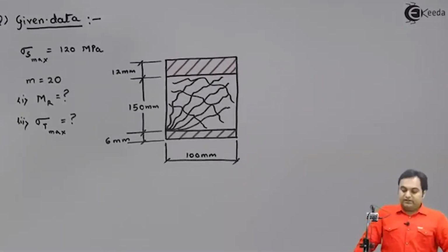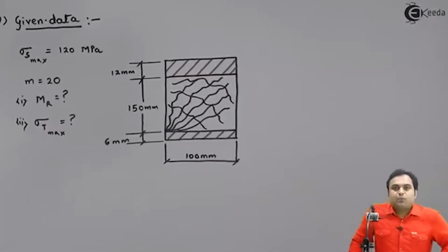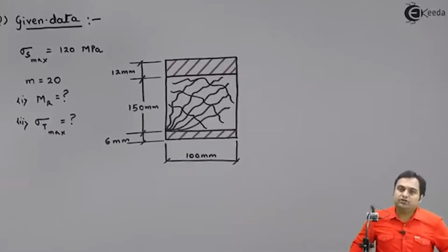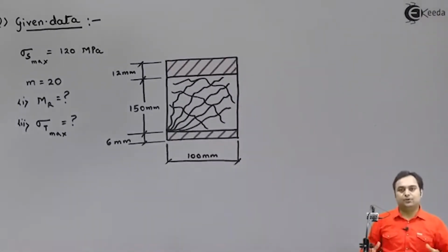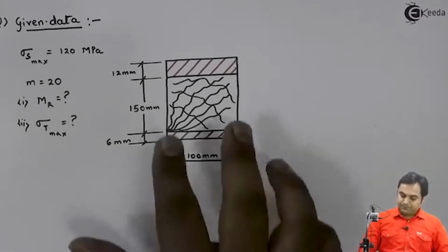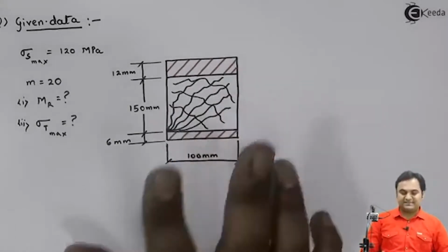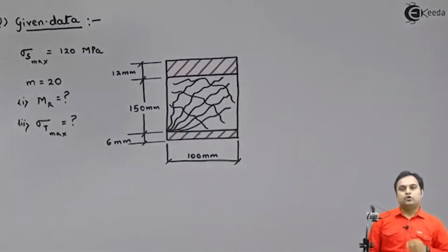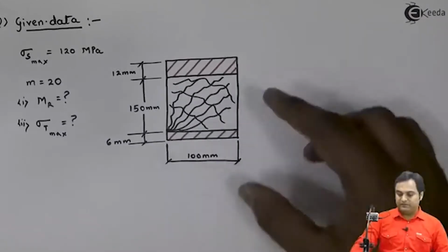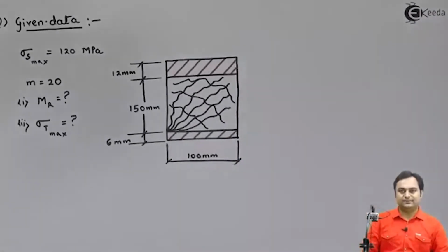Now, whenever they give you the problem of flitched beam, first of all try to get the location of neutral axis. Neutral axis is that axis over which the bending stress would be 0. So now here I have a diagram which is given to me. What I would be doing is replacing this wood section by steel section so that I have throughout steel. You can even solve this problem by converting the steel section into wooden section.